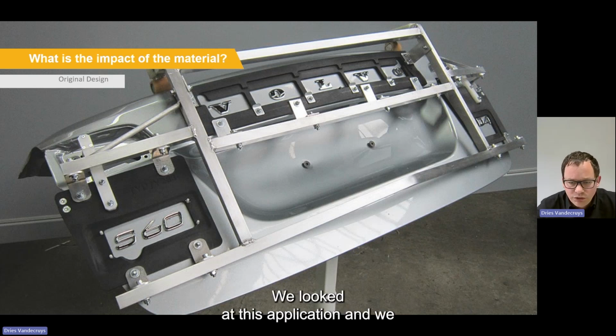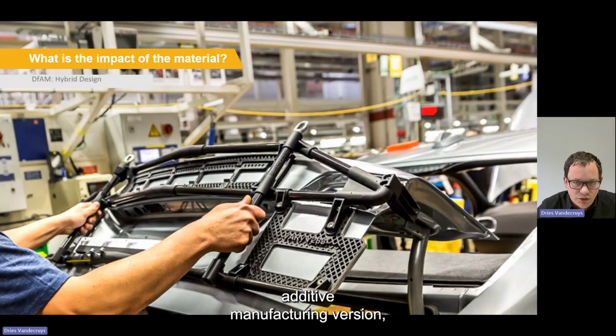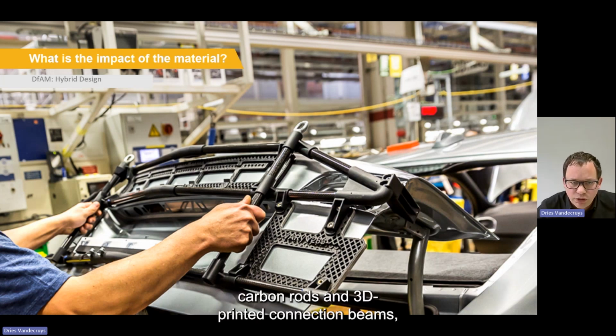We looked at this application and we redesigned an additive manufacturing version of this alignment fixture. In this additive manufacturing version, we focused a lot on having a lighter weight, and we thought, okay, how can we make it lighter and still have the necessary stiffness for this application? We decided to make a hybrid design, combining additive manufacturing with conventionally manufactured components. In this case, what you see here is a combination of traditionally manufactured carbon rods and 3D printed connection beams in order to make up the skeleton of this application.